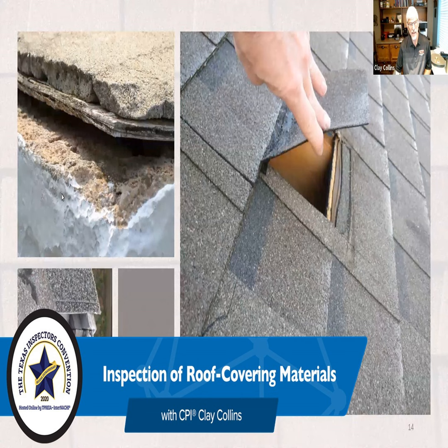Quality of materials. You always have a better quality shingle priced higher that is available. So you would not expect a low quality, whether it's 3-tab or laminated, to last as long as a higher quality shingle. You can't know that. You can't anticipate that. Yes, there are scales, there are tools designed that you would slip the shingle into, and based on where it comes, it's going to tell you how thick it is and therefore how long a life it's generally considered to have. I'm not lifting shingles to be able to slide that in there.